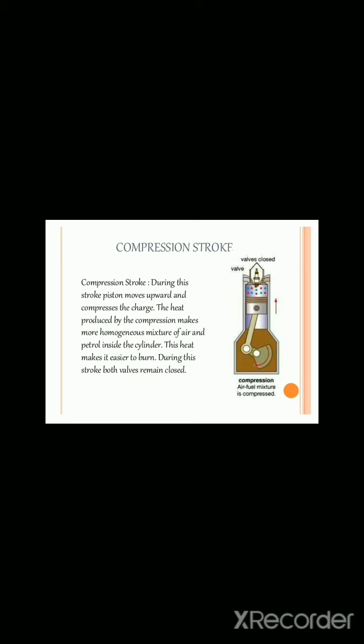Next one is the compression stroke. During this stroke, the piston moves upward and compresses the charge. The heat produced by the compression makes a more homogeneous mixture of air and petrol inside the cylinder. This heat makes it easier to burn. During this stroke, both valves remain closed, so it is a closed system. The air-fuel mixture is completely compressed.